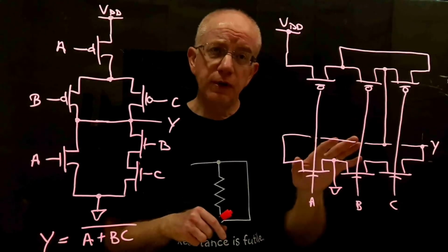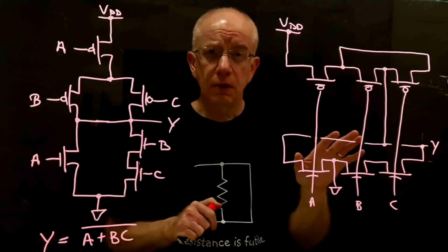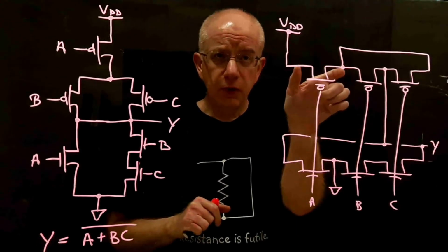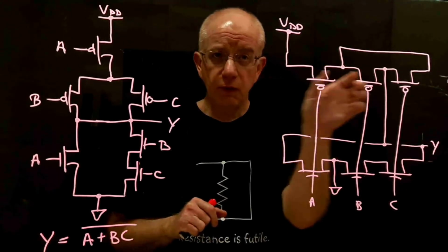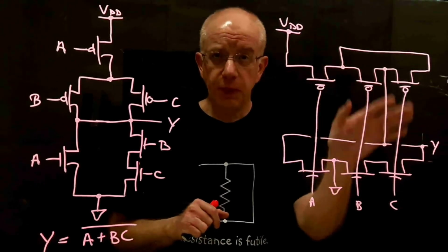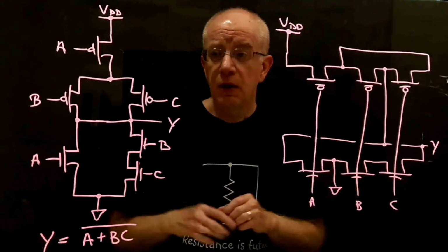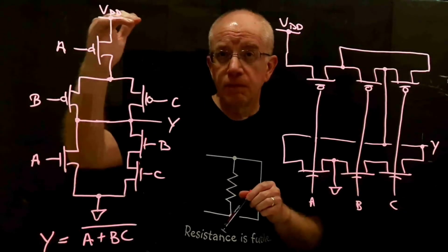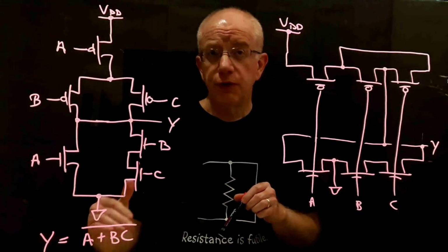I personally find this sort of quasi-schematic representation, where we're not really concerned with how wide this is going to be physically at this point, we're just concerned with the relative positions of the transistors in space. But there's more notion of space over here that maps onto physical space than there would be in the schematic, where we tend to arrange things so that higher potentials are higher up on the page and lower potentials are lower down on the page.